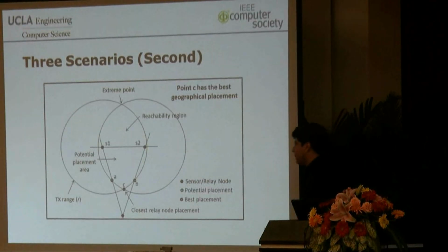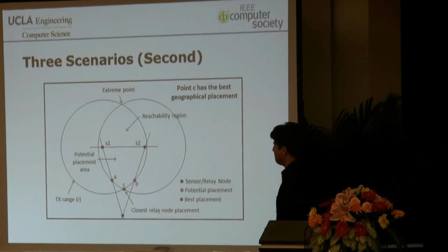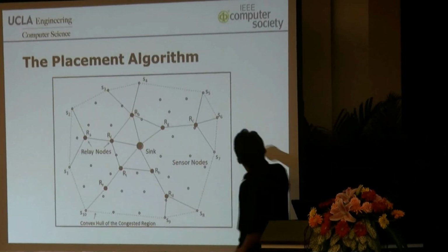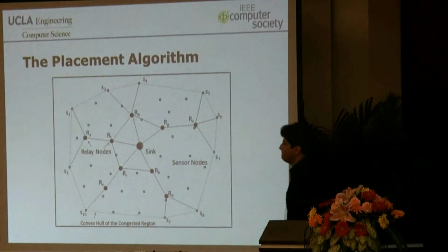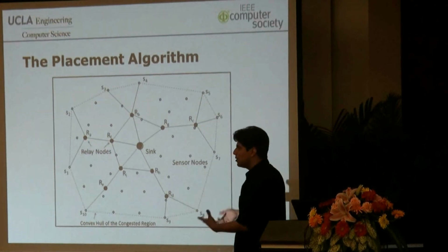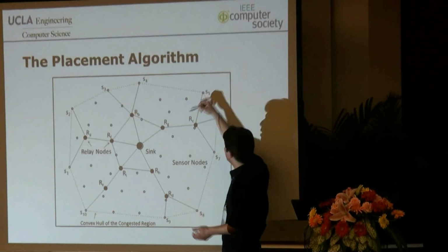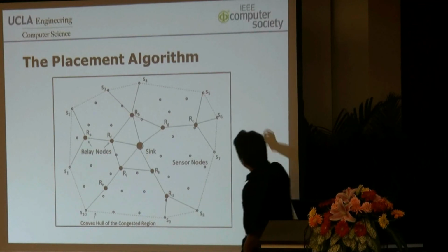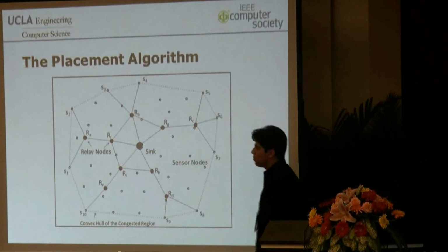I think you said that the relay should connect to as many sensors as possible, right? So I think of an extreme example: one relay connects to one source, and relay number 2 connects to 10 or even 100 sources. Then the overall delay would be very large, because the second relay would have to wait for 100 or more time slots. Yes, that's true. But there's also going to be a lot of contention. All those nodes are going to be asking to send their data, and there's only so much bandwidth that we can use, so you would have to wait. But at least the rest of the nodes would not starve. So that then becomes another problem, I think.